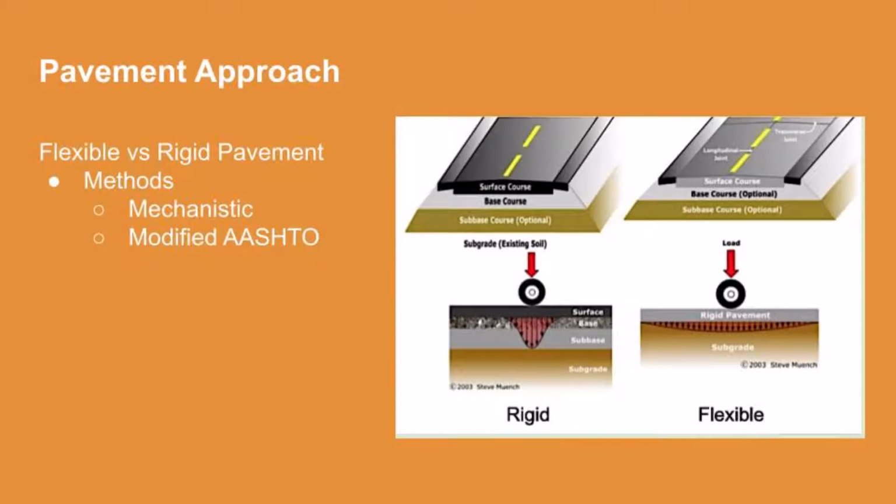Here we see the difference in flexible and rigid pavements. The difference is to focus on how each pavement distributes its loading. Rigid pavement is able to distribute the load over a wide area due to its rigidity and high modulus of elasticity, whereas flexible pavement uses sets of layers to help with the distribution since it does not distribute it as wide and well as the rigid does.